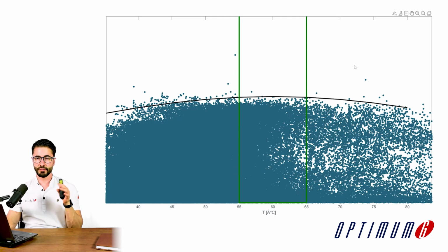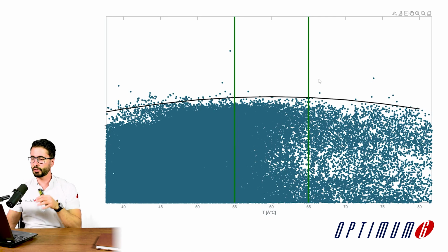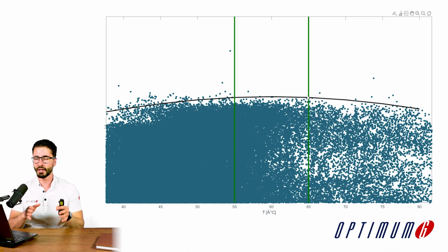So this is the plot that we've been analyzing of friction versus temperature. Here it's an internal temperature mostly connected to this parameter. We can clearly see how the temperature is influencing peak grip, and we can also define the 10-degree temperature window that we discussed. This is the temperature window that we want to be at.